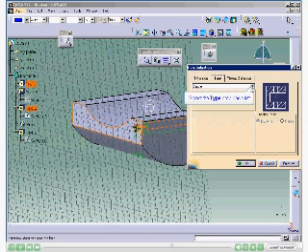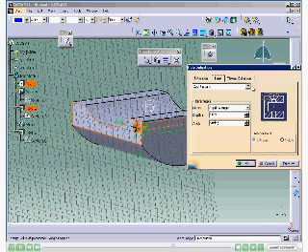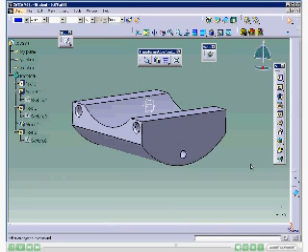Click on the Type drop-down list. Set the value of the Depth spinner to 5 and the Angle spinner to 90 deg and choose OK button. The right simple hole placed on the front face of the base feature is changed to a countersunk hole. As the hole on the left side is a mirror feature, it will get automatically modified.